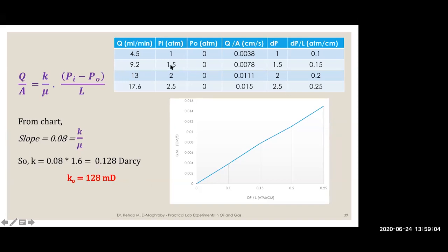Okay. So I want to point something out here. It's really important. If you look at the exit pressure, it is 0. So how can the exit pressure be 0? How come it is 0 atmosphere? Because it is a gauge pressure. You are using gauge pressure.